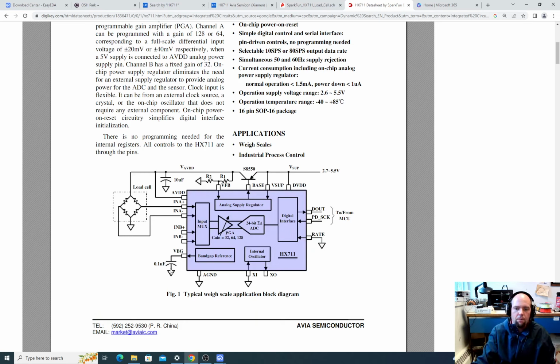The reason you have to have a capacitor here is because you want that voltage to be smooth. You don't want there to be any noise. If there's a little bit of noise in the supply or something, you don't want that to show up in your reference signal, because if you're comparing an analog value to a reference that's noisy, your data is going to be as noisy as that reference or that signal. The worst of both is what it's going to get. So we put this capacitor to smooth that out.